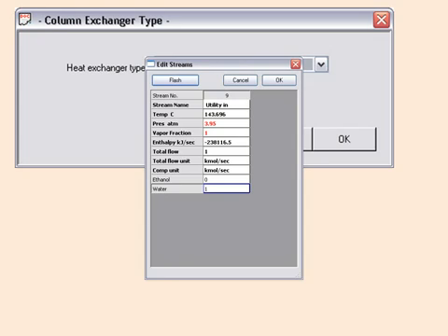We then would put in 1 for kilomoles per second for the water stream and allow ChemCAD to determine the actual flow rate for us. Note that I did not enter the temperature directly. I put in the vapor fraction and the pressure, and ChemCAD calculates the temperature. Should you try to put in all three, you would find that ChemCAD would give you an error, and then you would have to choose 2 of those 3 to enter.